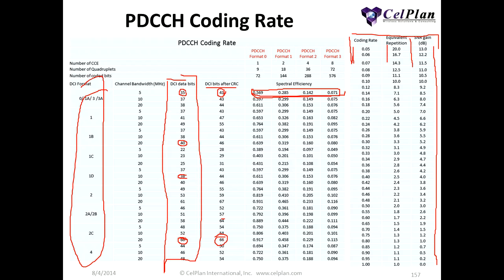So what it means, suppose I have a UE that has an SNR of minus 5 dB, and I know that I need to detect the signal at plus 5 SNR, so I will need to choose an SNR gain of 10, so I will need to use a coding rate of 0.1, and I go here and I have 0.1, I probably will need to be here, okay, so if I am using DCI 2.